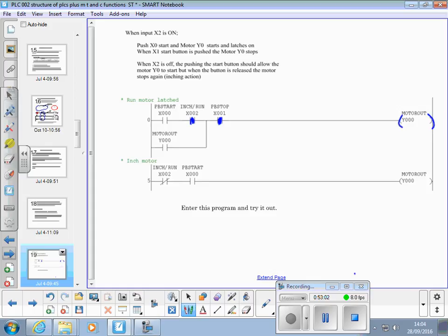We think this will work, but what happens is, remember your program scan time now, and how it scans the program. We push this button, the program tells it to turn that on, but then when it interrogates, that line says in memory, turn on Y, but not the real Y0 yet, because we haven't got to the end instruction. It then comes along to your next line of program, and this line of program says, turn it off. So it never comes on. Yep. Agreed?